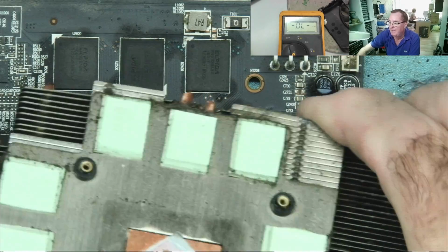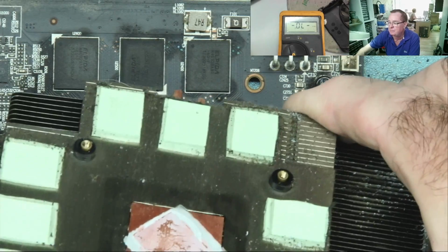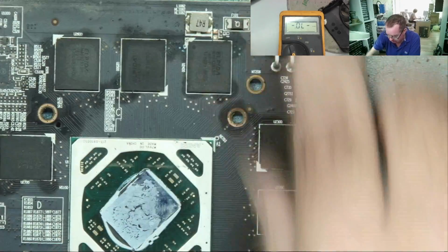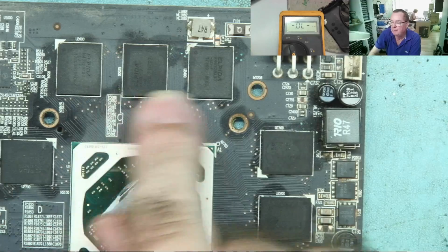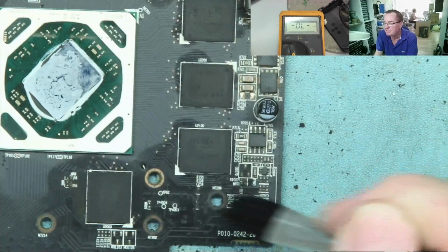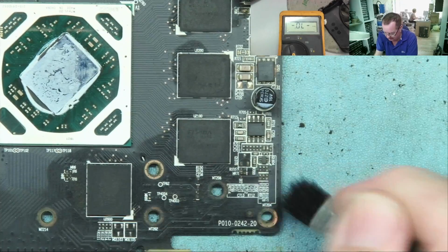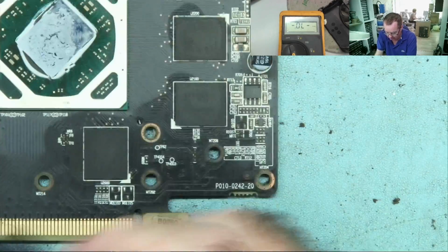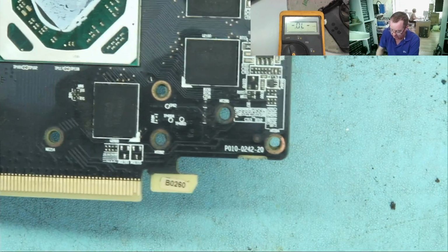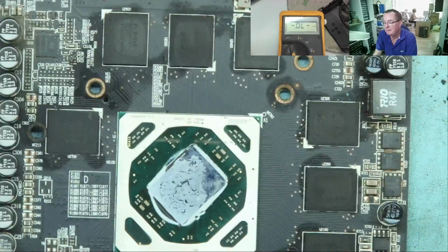These are the pads that effectively fit on the chips, and they release a kind of, well, it looks oily but it's dry, and that's what we often see. If you see this, that's a good indication that this has been running hard. So again, if you can't find anything else wrong, RAM is a suspicion, a faulty RAM chip.